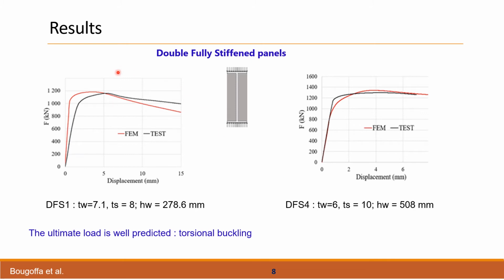And the instability here is observed with the decrease of the load, but with large plastic deformation, as seen here in this part. The finite element model also represents well the behavior of the specimen regarding the load-displacement curve, except for the stiffness here, and also the failure mode.